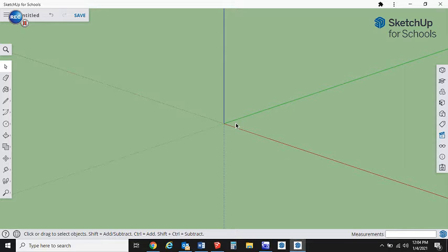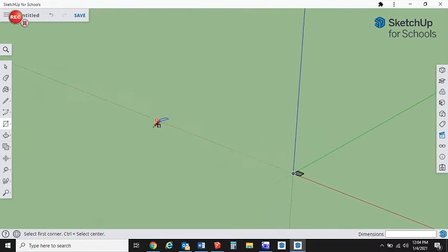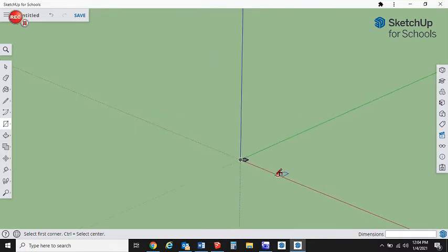Okay, so rectangle tool, R for shortcut, or it's over on the left hand toolbar, and we're going to click, release, and then drag, and that's always the key with SketchUp, is to click, release, drag, and then we can type in. You know you've done it correctly if you have your hand off the mouse and you can still move it around. So 20, 20, enter, and you're going to say, well, where'd that go? Well, it is there. We just have to really zoom in, and it gets kind of tricky. Remember, wherever you point your mouse, that's where it's going to zoom to.